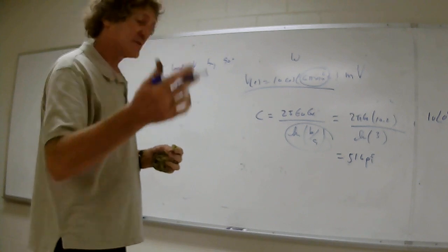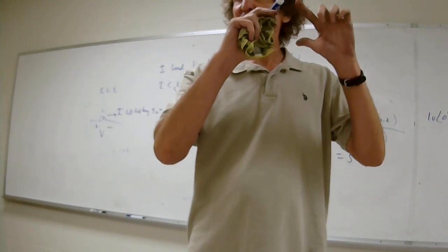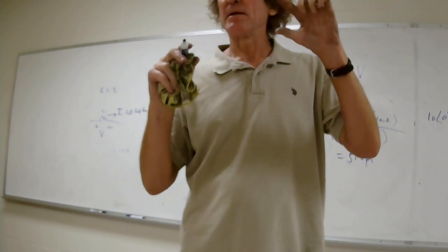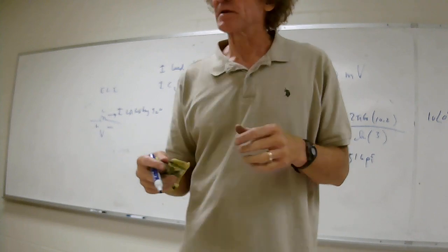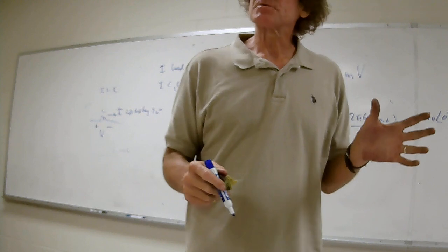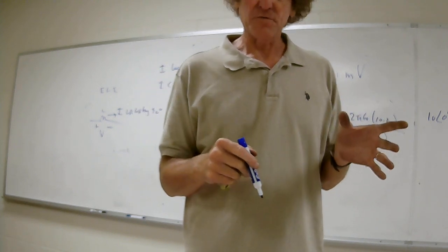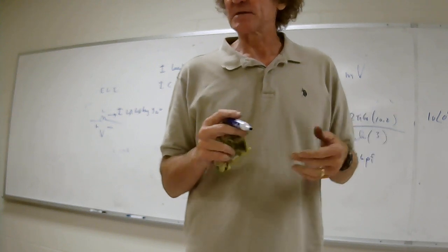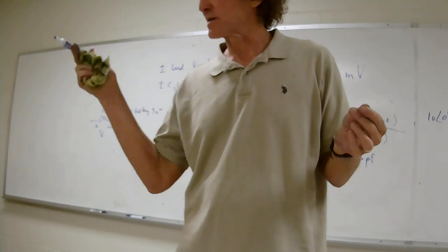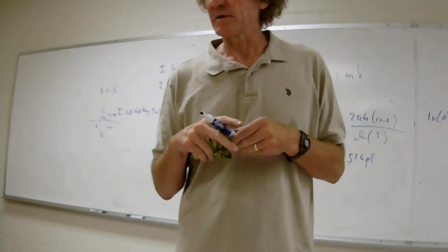So when you have a transient on an inductor, say you put a voltage on it, the current, just as that transient happens, is 0. It's going to start going up because you can think of the inductor as something that requires momentum to get current through it. For a capacitor, it's the opposite. As soon as the voltage is felt, it dumps tons of current through it. All right? And that's what goes on. But with a capacitor, as time goes by, it looks like an open circuit, and an inductor like a short. All right, that's the reasoning behind it. Okay.